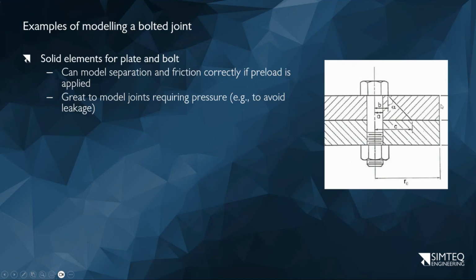The load is transferred in shear on that face, but also because that force is in the center, there's a bit of a moment about that face, meaning I need to counteract that moment. Now, the way that it actually is transferred is in compressive stress distribution over that face. So if the stress on this side is, for argument's sake, higher than on this side, I've got a bending moment towards the left. So that bending moment is not directly transferred to the bolt itself.